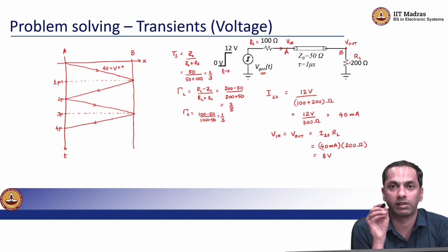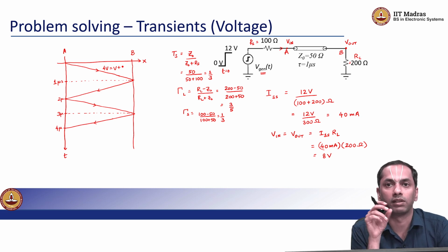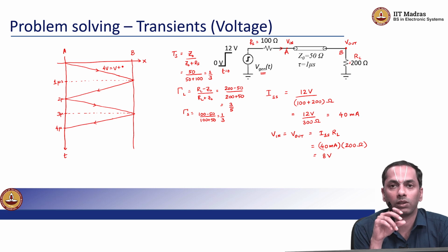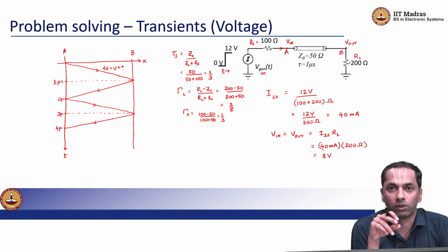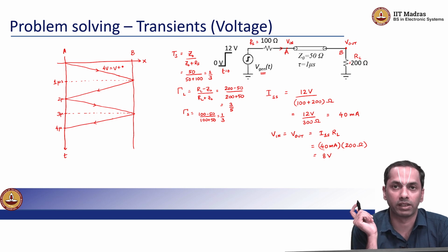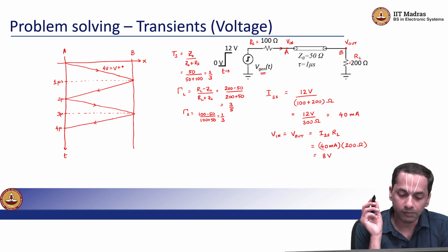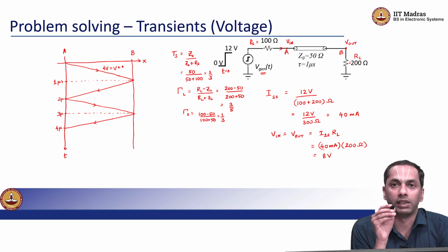So, it is slowly charging the entire transmission line, and think of all the little distributed capacitors that we saw. They are all charging up to hold 4 volts across the plates. And you can also consider some amount of current. We will do the same analysis for currents in the next part, where we will talk about the inductors also getting charged. So, we have a 4 volt signal being sent across the transmission line.